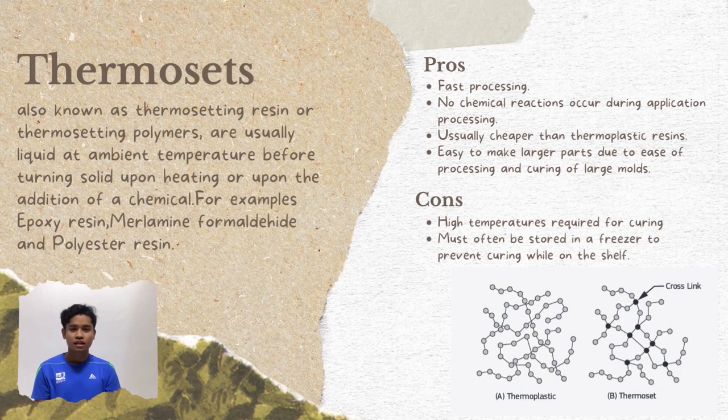Durability. Thermosets are highly resistant to heat, chemicals, and physical stress, making them highly durable and long-lasting. Strength. Thermosets have a high degree of mechanical strength, making them ideal for structural applications that require load-bearing capacity. Fire resistant. Many thermosets are highly resistant to fire, making them ideal for use in applications where fire safety is a concern. Thermosets are cheaper than thermoplastics, and the con is the high temperature required for curing.